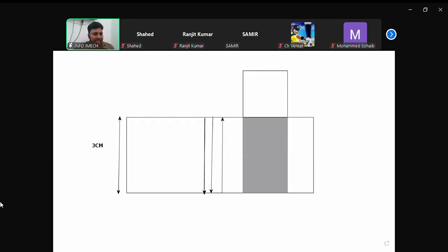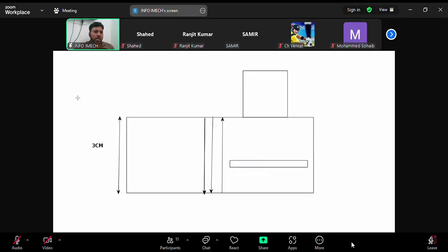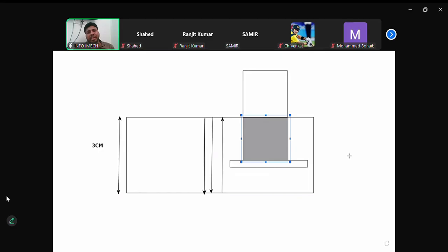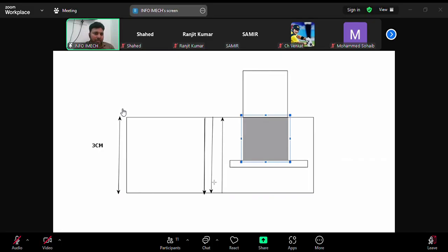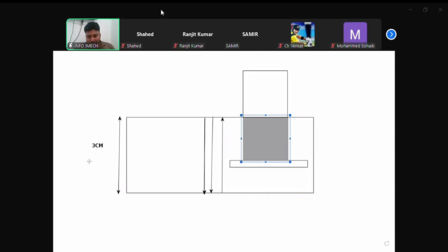But in second case, your workpiece has a defect like this. So now the sound which your probe is sending, the total sound is reflecting from the defect. So your machine will give defect echo because sound is reflecting from the defect, it is not going to the back wall. Second case. Am I correct?